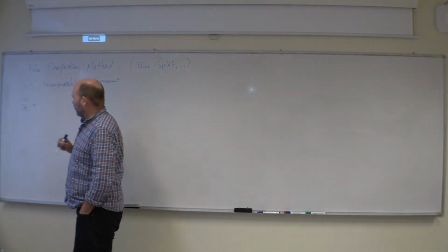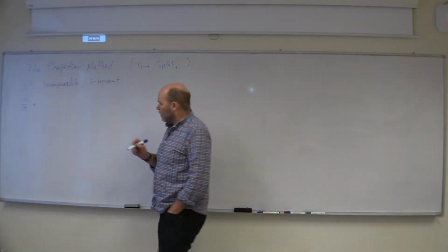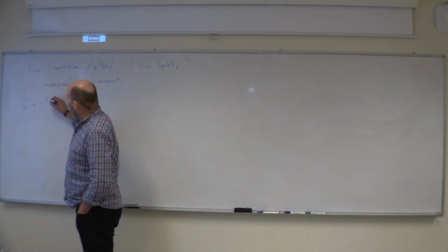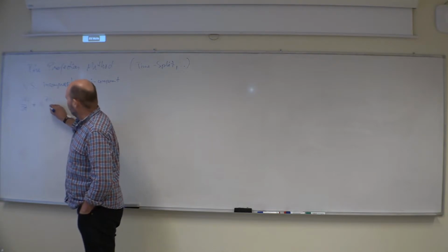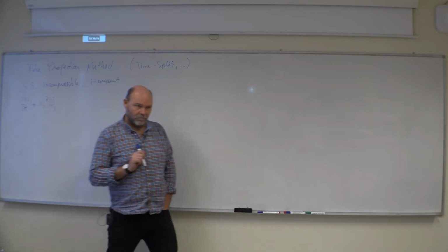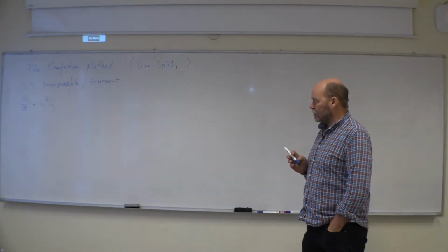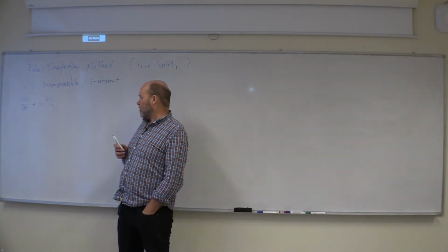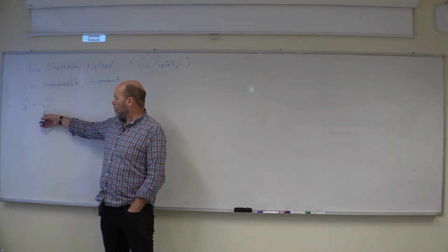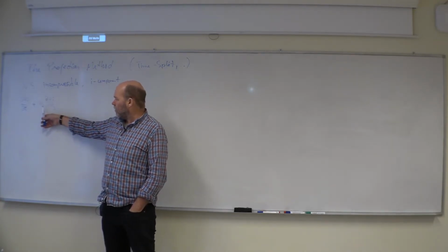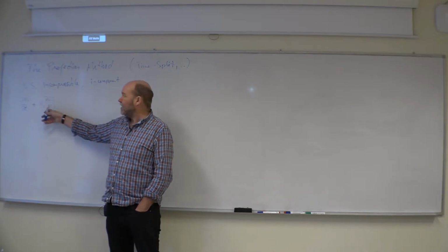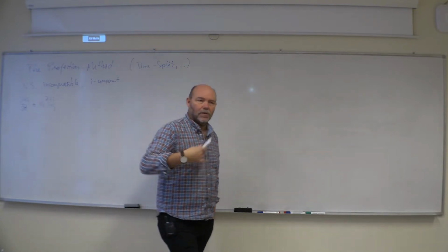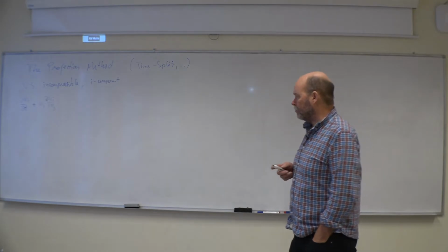And then we have the convective terms. How do we write that one? Then I write u_j, and then I take the derivative of u_i with respect to x_j. You see the trick for this tensor notation? When the same index appears twice in a term, you have to sum them together. So here, this term will now read, if you wrote it out, u du/dx plus v du/dy plus w du/dz. So there you'll have all three terms, the nonlinear terms.